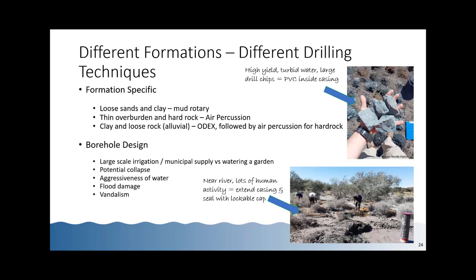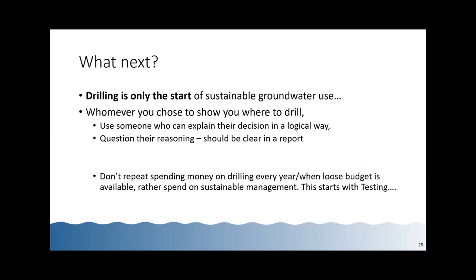So now that you understand more about what groundwater looks like, you need to bear in mind that drilling is actually only the start of sustainable groundwater use. Whenever someone shows you where to drill, make sure that the reasoning behind that position is logical. Ask them, why did they drill below the dam wall? We all know dam walls leak. Ask them certain questions that they should be able to answer in a clear report so that you can revert back to it at a later stage.